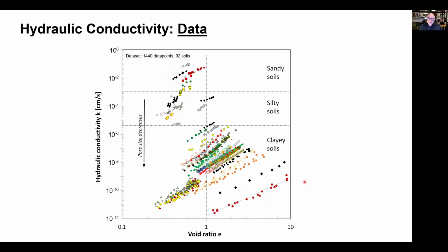Therefore, we would like to understand what are the parameters that control this. And if you have an intuition that permeability is controlled by porosity, you really have to reassess that intuition, because look, the soils with higher porosity are the clays, yet they are the ones with the lowest permeability. So it's not following the line that higher porosity, higher permeability, and there must be something very important and fundamental behind it. So let's take a look at this data now and try to come up with an estimate of the pore size, because that is where the fluid is flowing through.